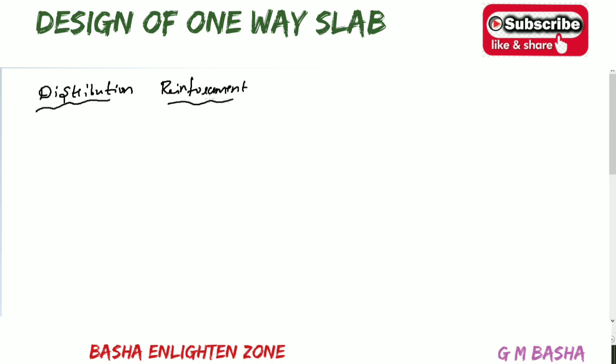So area of the steel. Already for the distribution reinforcement, the minimum area means 0.12% of gross cross sectional area. So what is the percentage? Already we calculated that one. That will be equal to 174 mm square. So that much of the minimum reinforcement will be required in the distribution reinforcement side also.